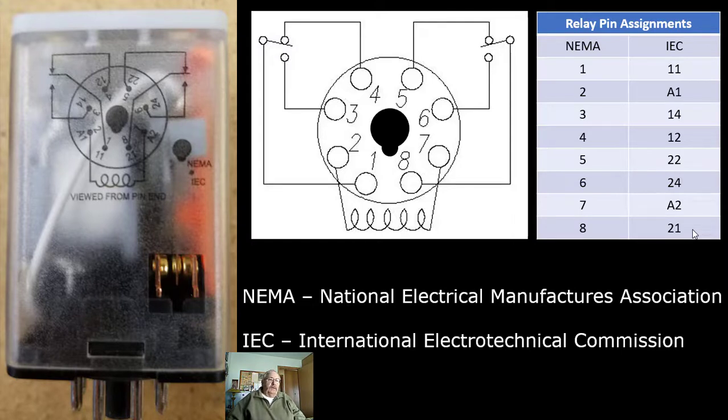IEC is becoming more prominent here in the United States. They're trying to standardize things. So you're going to be seeing less and less NEMA here in the States and more IEC. So I like the fact that this relay company is showing both sets of pin numbers or terminal numbers for us here in the US